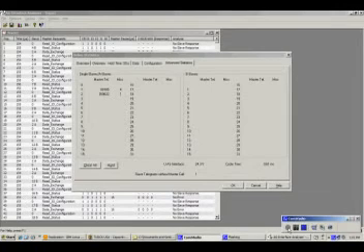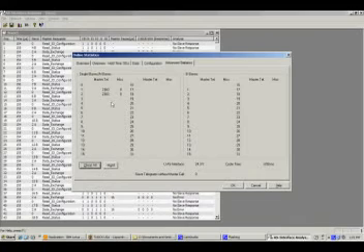Now if I go ahead and add node number 1 to my system, you will see that already I'm starting to track messages to node number 1. The missed packet count you see here is because I was jiggling it as I put it on, so it wasn't making contact until I firmly tighten it down to the flat ASI cable. But I can hit clear all here and have it reset, and you'll see that it tracks correctly.